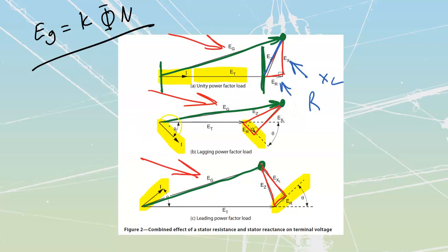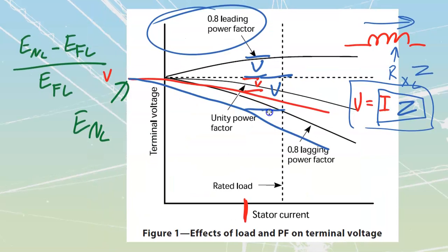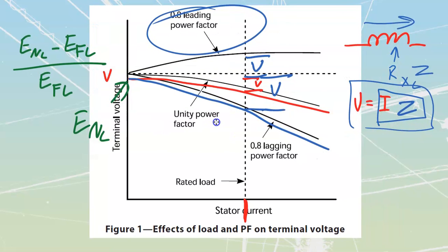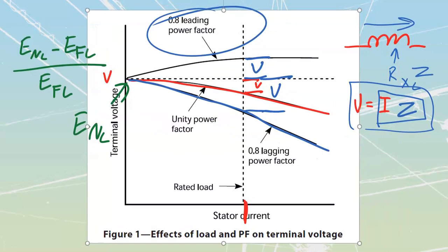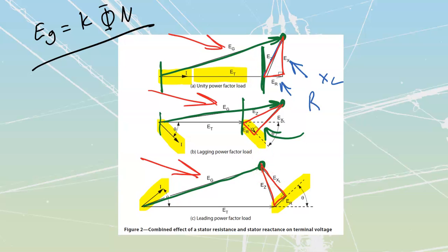If I have my generated voltage in my triangle, but now I twist that triangle in like that, I'm going to have a shorter terminal voltage. My amount of terminal voltage is going to go down. We see that reflected right over here on that lowered value of terminal voltage. And if I take a look at my last one down here, if I keep this anchored together and now I twist this triangle out like that, because it's matching this current line over here, I'm now going to have a much larger value of terminal voltage.